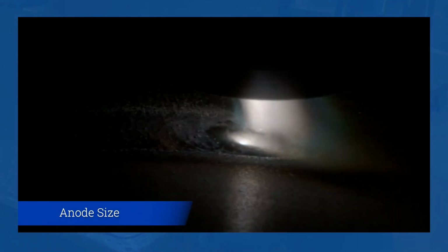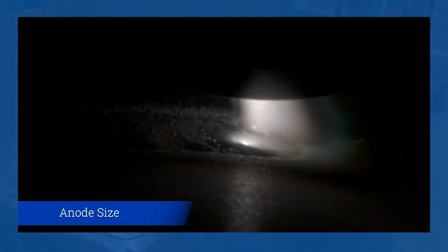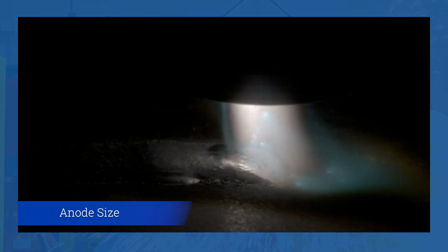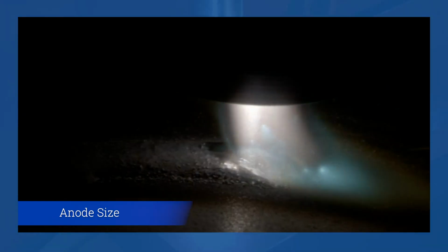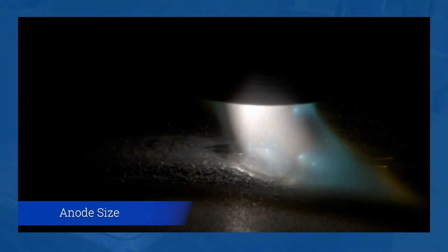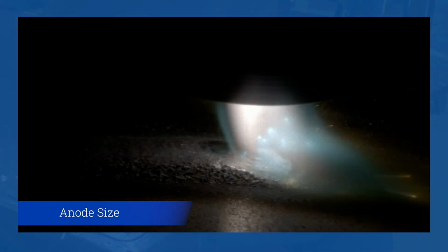Let's talk about anode size. With a plasma torch, you need to match your current to your anode diameter. In this case, this is optimized for 120 amps. So here we have an oversized anode, so the diameter is too large. What we're doing here is we're not collimating the arc properly. You might as well TIG weld at this point. So if you ever see this, one of two problems: you have the wrong anode, or possibly your tungsten is too close to the end of the anode.